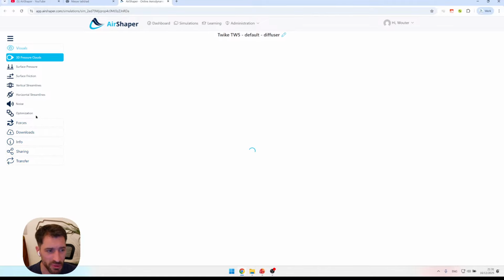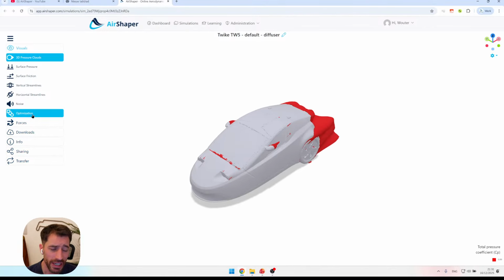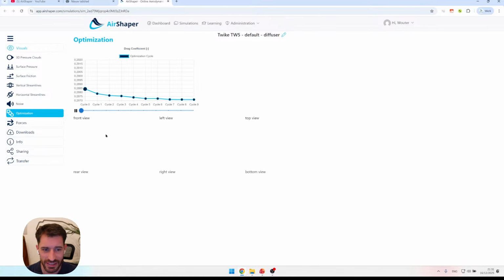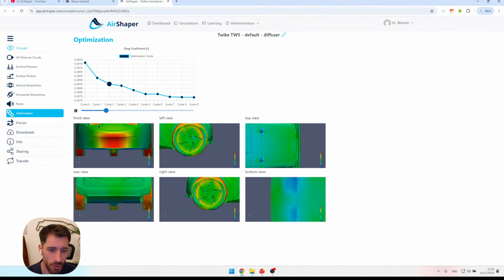Then comes a very important one, which is the diffuser on the car. It's slightly more difficult to see on this one, but what was happening is we had a fairly straightforward diffuser, just an angled surface upward, which started to go up as soon as the hard point of the chassis was passed. In this case, the software was telling us, well, instead of using a straight line, it started denting the diffuser.